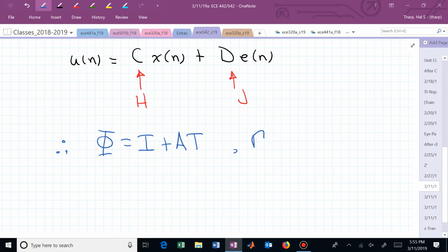How could you find capital T? I should see a bunch of thumbs up in the air. That's our rule of thumb, isn't it? 30 omega sub n. You would find the highest frequency in the A matrix, find the eigenvalues of the A matrix, and find which one is furthest away from the origin, and find that distance. That's your natural frequency that you would use. That's omega sub n. And you would say, oh, I need to go 30 times that.